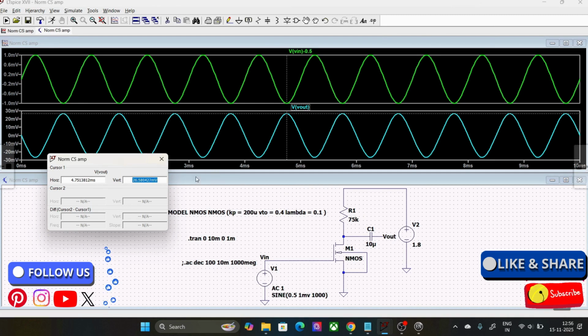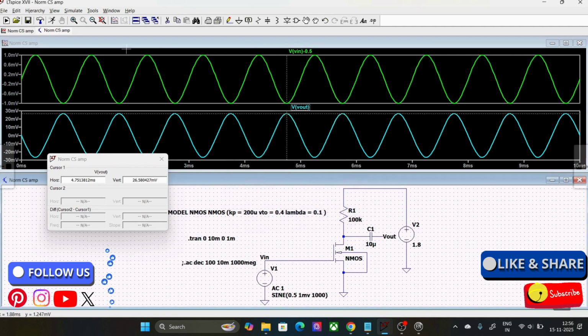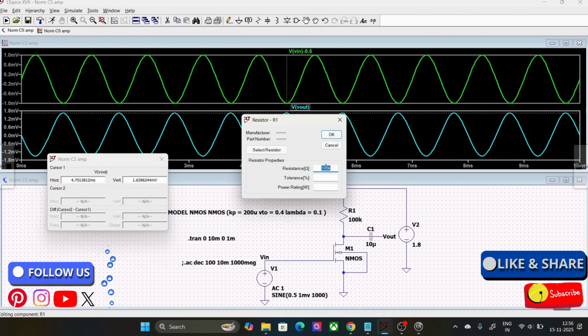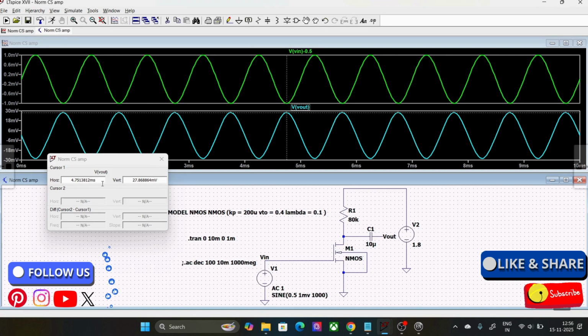If I change the value from 75k to 100k, let's see what gain we get. Now the gain suddenly decreases. So if I keep it at around 80k, my gain is around 27. So this is the maximum gain that we are getting from a common source amplifier.